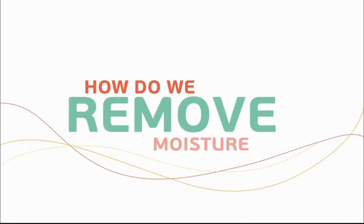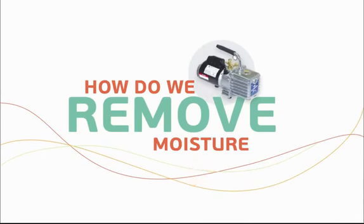Moisture is removed with a vacuum pump, which lowers the pressure in the system to the point that water is boiled or evaporated. The pump can now easily remove this water vapor. Vacuum level is measured in microns, so we need an electronic micron gauge to verify proper vacuum. We need to achieve 500 microns or less to be sure that the water is vaporized and effectively removed. A new correctly sized filter dryer should always be installed anytime the system is opened for service.